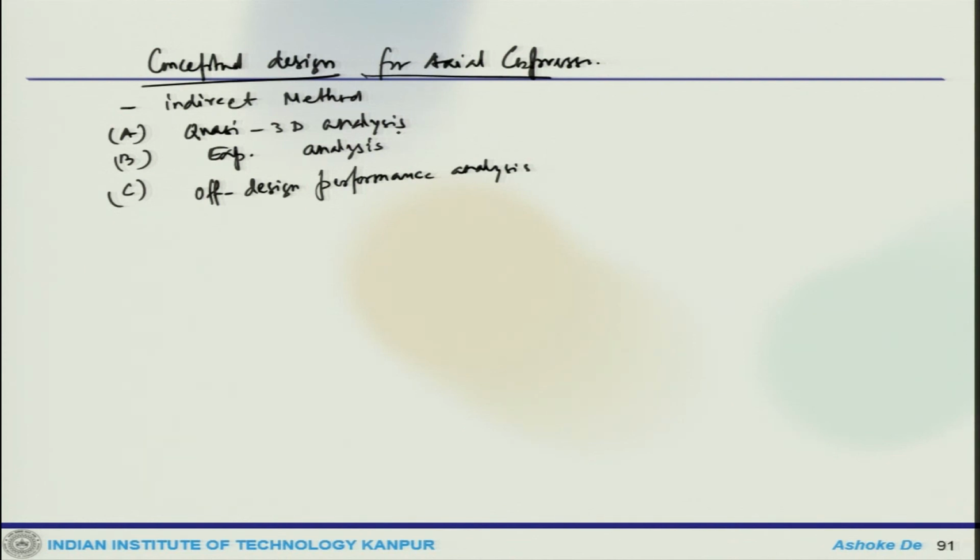In the details of such a step, you can have a choice of compressor data like rotational speed, axial velocity, and then the dimensions of the annulus, and then you can determine the number of stages.